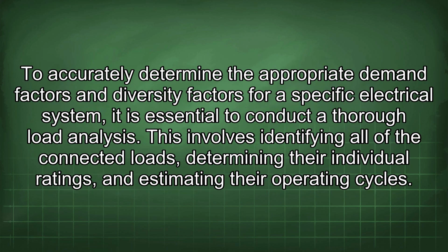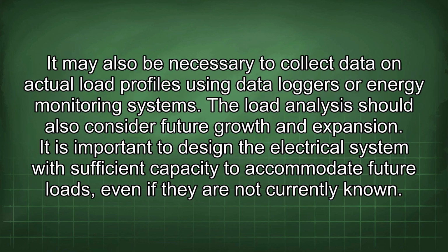To accurately determine the appropriate demand factors and diversity factors for a specific electrical system, it is essential to conduct a thorough load analysis. This involves identifying all of the connected loads, determining their individual ratings, and estimating their operating cycles. It may also be necessary to collect data on actual load profiles using data loggers or energy monitoring systems.